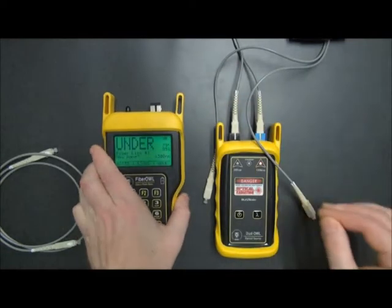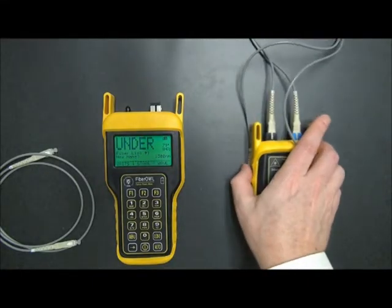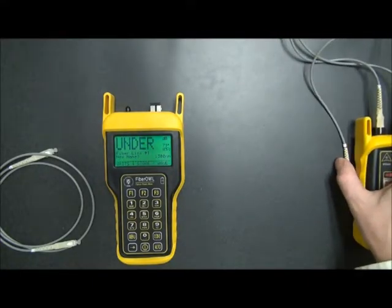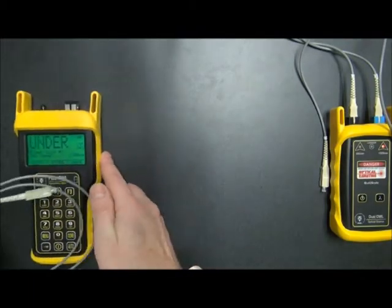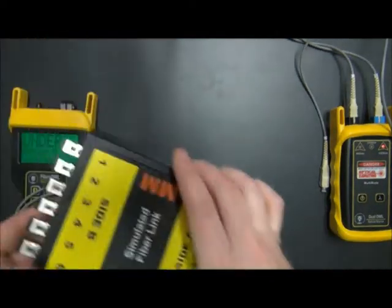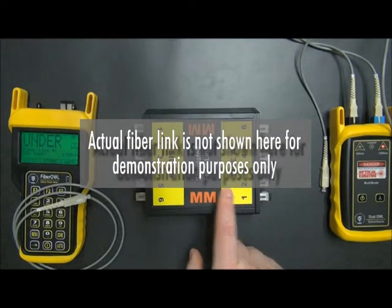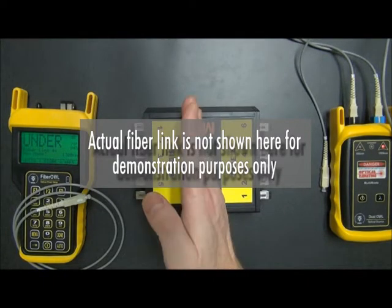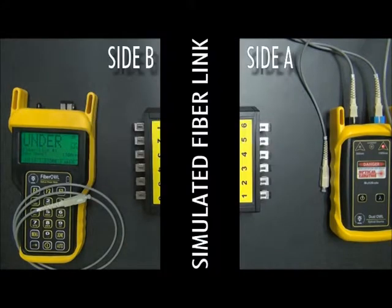And what we need to do is take both units to opposite ends of the link. And what we'll do is we'll do that here. So we'll take the light source to its side. We'll take the power meter with its reference cable to the other side, and then we'll again use our simulated fiber link here. As you can see, side A, side B. So this could be a different closet. You know, this could be one closet, and side B could be in another closet.